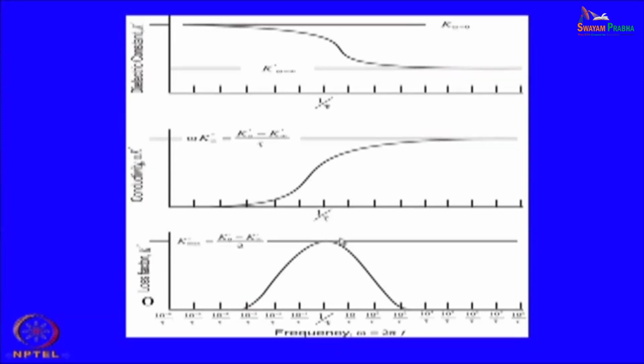Ideally, in a capacitor we would look for where the loss is less, because if the loss is high, not only are you losing a lot of energy, but also because of the relatively large current, the whole material will get heated up. So, there will be Joule heating. Therefore, in practice we should look for a dielectric material where the loss is low. That is the normal practice.